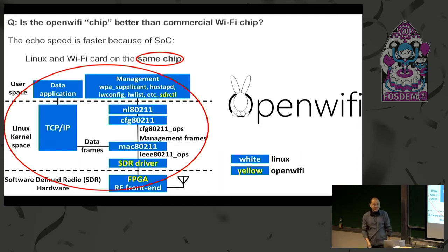It is the Xilinx on-chip bus, which is the AXI Stream or AXI memory mapped DMA controller. So that's why we have to develop the Linux driver for this quite special on-chip, low latency, high throughput link for our Wi-Fi design.